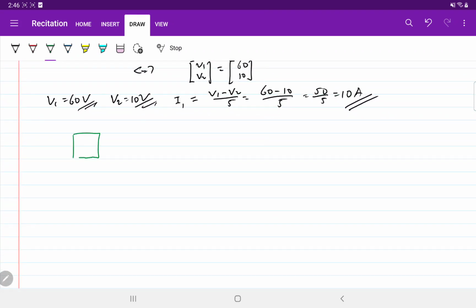When we have something like a voltage or current source or even a resistor, and we define the voltage as plus minus, and the current is going out, then the power is negative, so power is minus VI. It means that this element is delivering power.